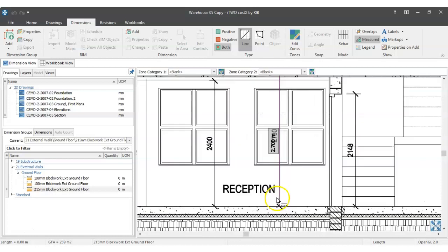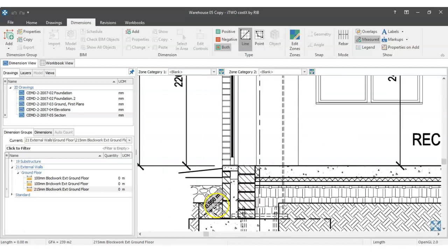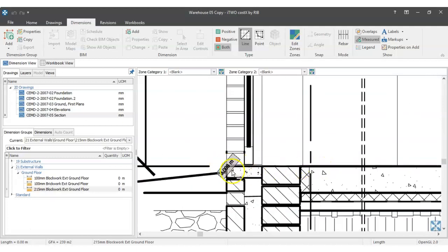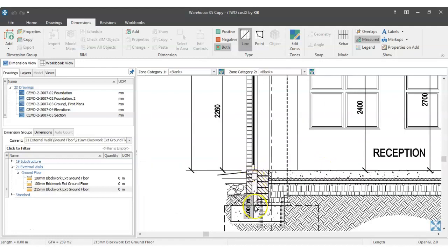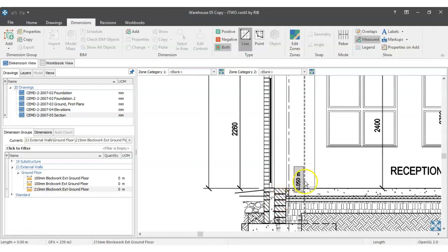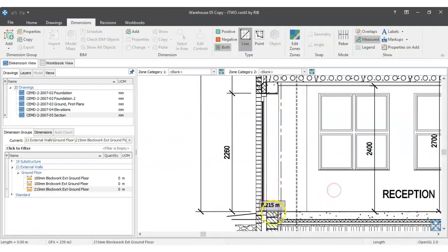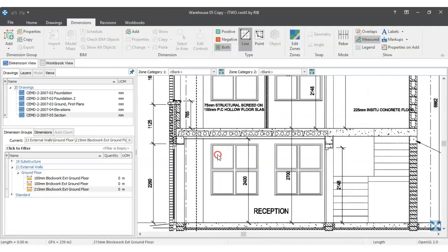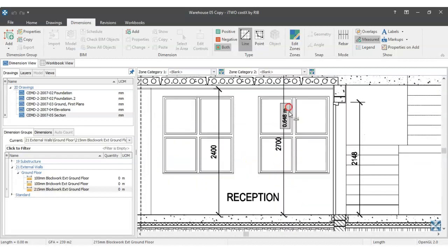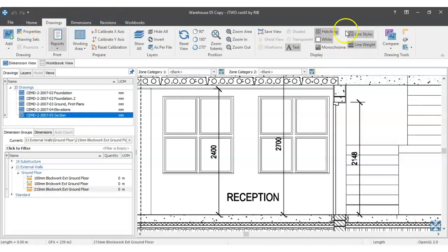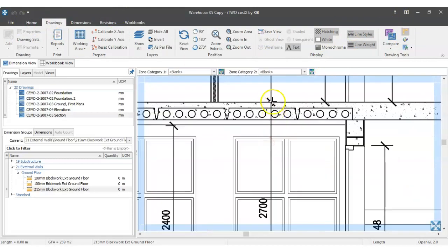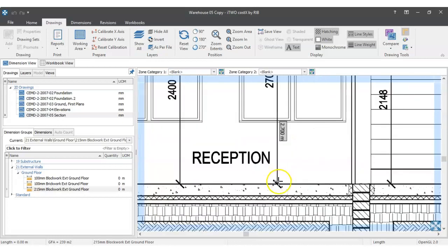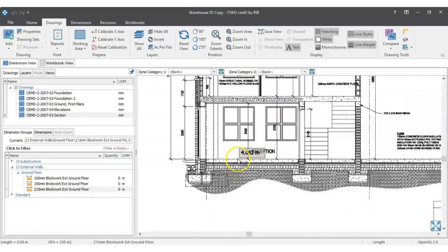Let's figure out first what the height is from my ground floor. Now remember, we've measured our rising walls with the substructure because everything below DPC level, which is right here, our ground floor level, ground floor finish level, is part of the substructure. So those rising walls would have been measured before. So I have as part of the ground floor from that DPC level, ground floor level, up to first floor level. So what's that dimension? Well, I can see that I have it there. It's 2.7. If you wanted to do a quick check, drawings, little measurement rule, and we're going to click the top, right down, and it is 2.7. So I'm happy enough with that. My ground floor to first floor level, story to story level is 2.7.